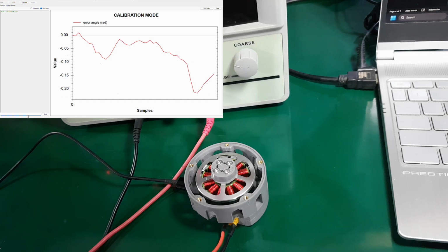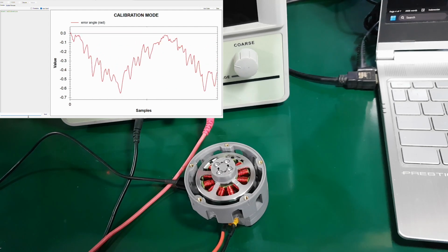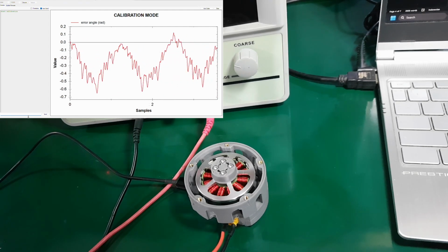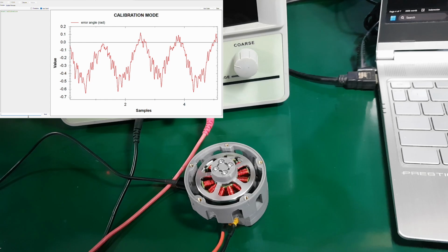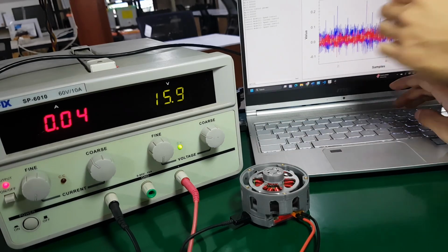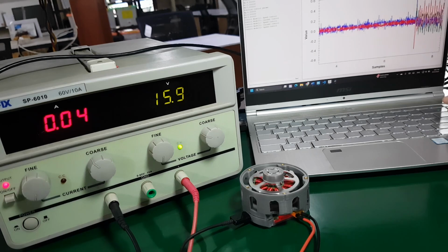This becomes a critical issue, especially for encoder calibration. Should we really have to recalibrate every time the system is restarted? Of course not. Therefore, in this video, we will cover two fundamental solutions. How to create a USB communication interface for modifying parameters and strategies for saving those parameters into non-volatile memory.